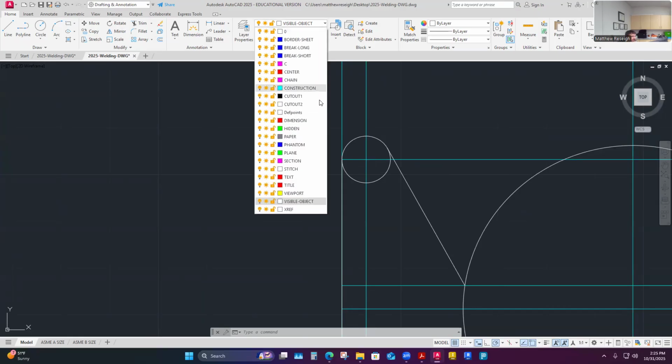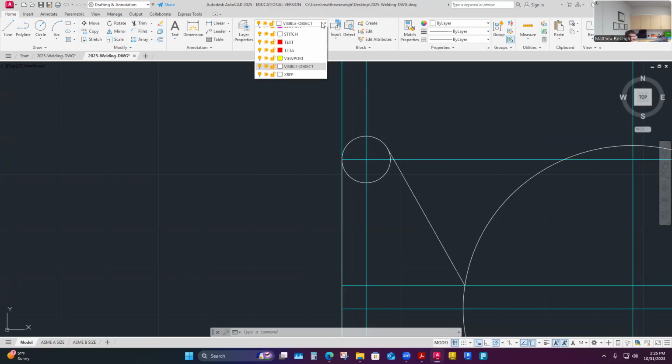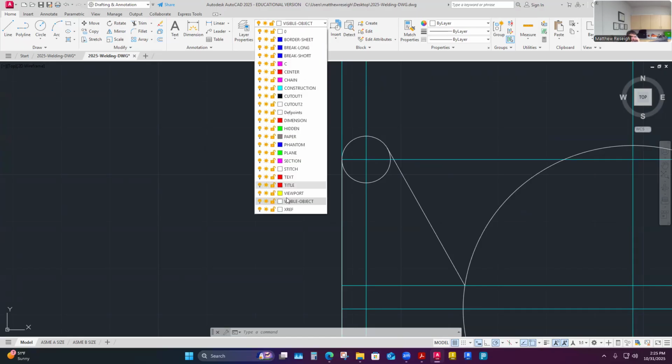The other thing we haven't talked about with layers is, yes, you have your layer, and to select it you just go in here, choose it, click on it. But you could lock a layer so it's going to stay. We don't even need to worry about this. All my layers are currently unlocked, but we could lock them almost as a security measure so things don't get moved or bumped while I'm working on other geometry. I don't want to grab some other layer's construction work or actual work and move it. I can lock it down so it locks me out of messing it up.